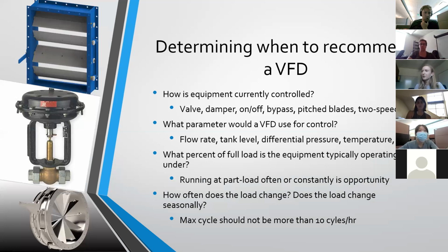And I would guess that this is more of a common issue with something like an air compressor, where you see fluctuating use of compressed air throughout a facility at different times of the day. And so you might have more cycling. In pumps and fans, I would think it would be more consistent. But again, that's something to ask your customer, figure out how often things like that are changing. And that's also something you could ask for trends on or measure yourself to try and figure out how often your equipment would be cycling.